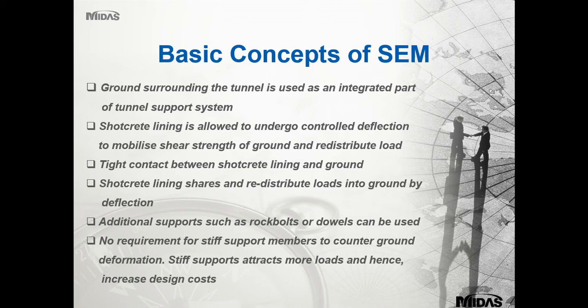Additional supports can be provided in terms of rock bolts or dowels, and grouting can be used as well, in the form of drilling, grouting and doweling. You can also have no requirement for stiff support members to counteract the ground deformation, where you've got really good ground, since stiff supports can attract more loads and hence increase design costs. So the more you try to avoid putting these in place, the lower the cost will be.